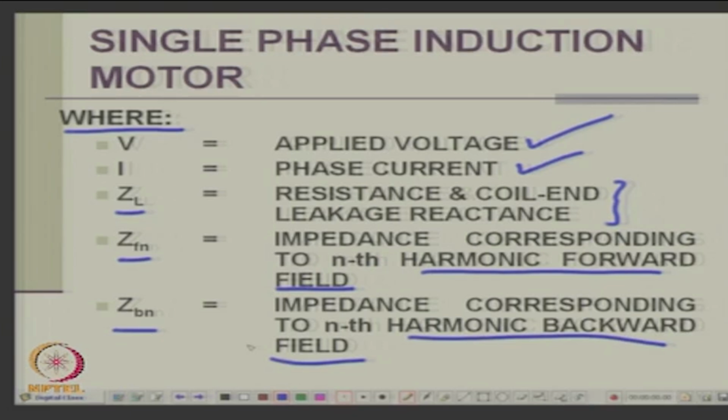Sir, we are considering V as a stator voltage, applied voltage. Yes. Then sir, rotor currents will have some effect on that also, no? Because rotor current will induce some voltage. Yeah, that is why rotor currents are induced. What will it do? If a current is induced in the rotor, it will produce an MMF in the rotor surface, isn't it? And the forward flux will be changed because of rotor currents. Voltage is induced not due to MMF, it is due to flux. Which flux? What is the net air gap flux?